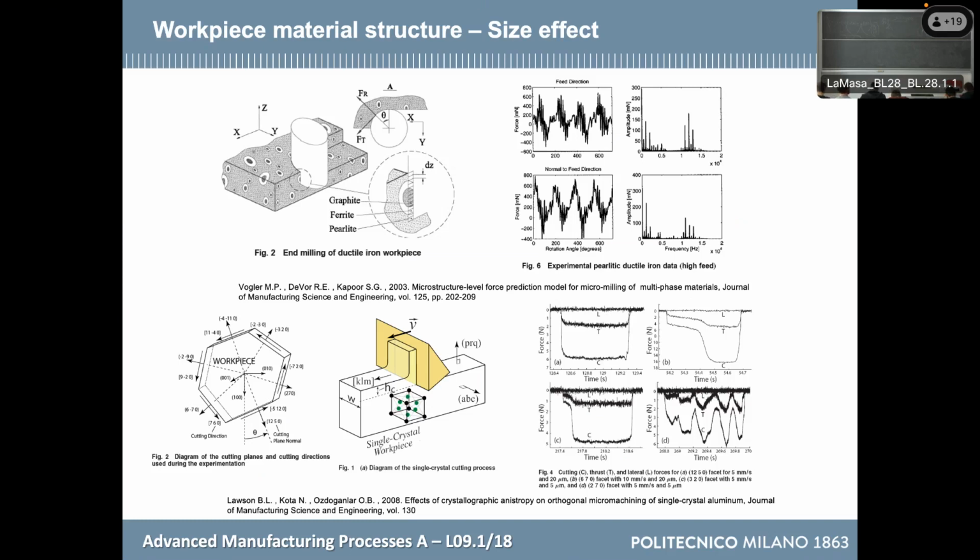In the second paper here, you see another effect that is due to the orientation of the grains. In this paper, they machined copper, if I'm not wrong, but it is aluminium. It is a single crystal aluminium. You know that in metallurgy, you can let some grains grow, and you can even make a turbine blade, as I've already told you, made of just one grain. Once you have that perfect lattice, I have said last time that the material resists more.